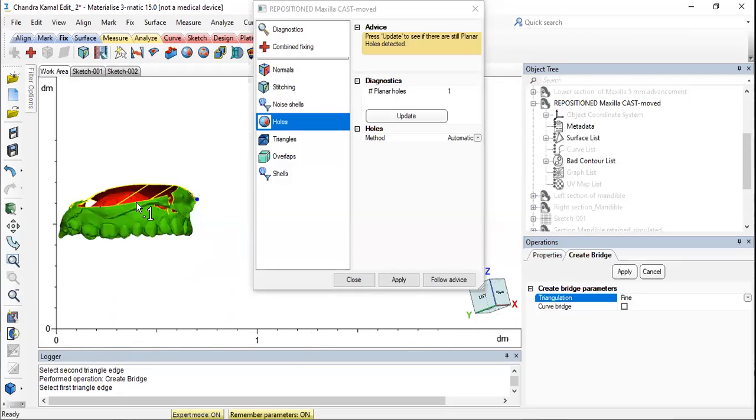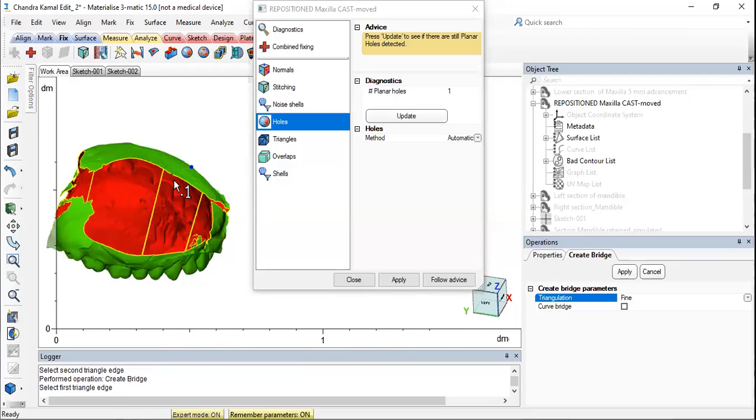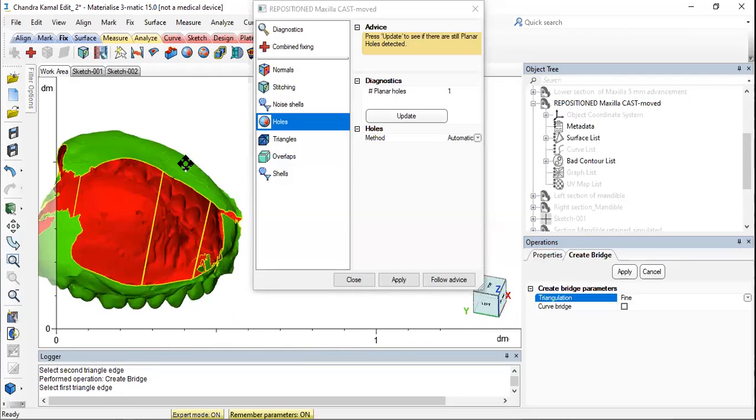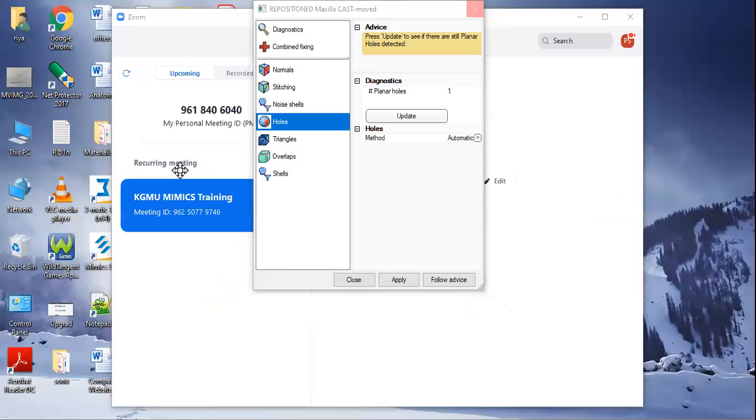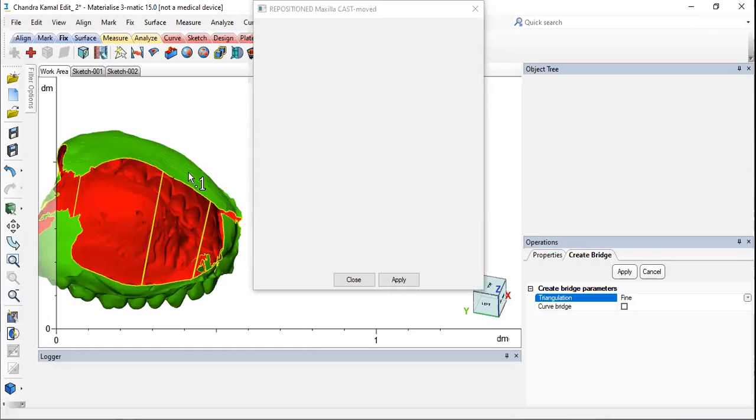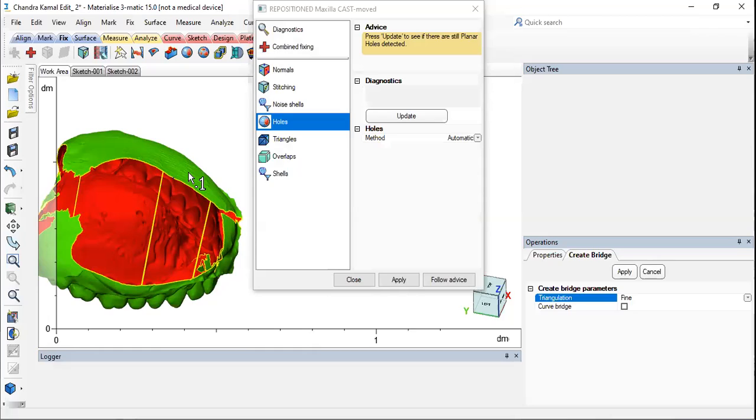Yes ma'am, that's not a problem, but you don't require fixed files in Mimics. As I said, any STL you make in Mimics you have to fix before printing. But for repositioning and such in Mimics, whether the file is fixed or the surface is open, it doesn't have any impact per se. Here in Threematic, fixation is very important. Without fixation, some steps will not happen correctly. So in Mimics you can proceed irrespective, but in Threematic, of course, once you import the file, you can first go for fixing the files. That shouldn't be a problem.